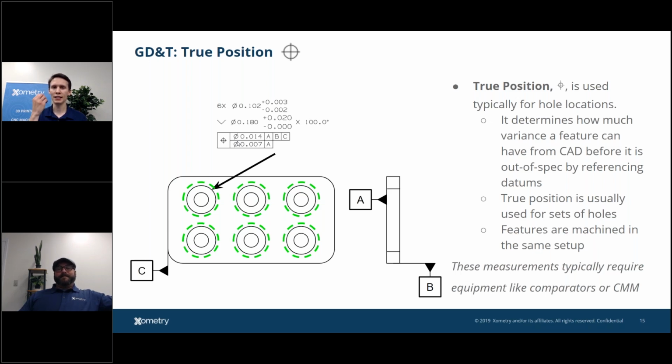Yep. So anytime you're tightening a tolerance, especially if you're making an over tight tolerance for the actual purpose of the part, you're incorporating risk, which could add lead time, increase scrap rate, you name it, and you may not always need that work. So just to talk about interpretation of this, this is a very typical thing I could see here for a countersink hole.